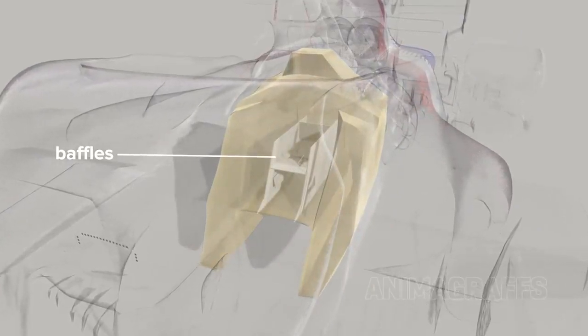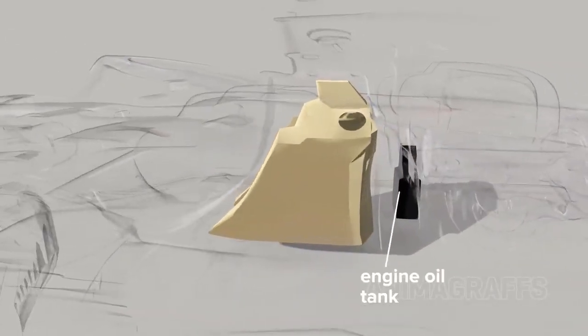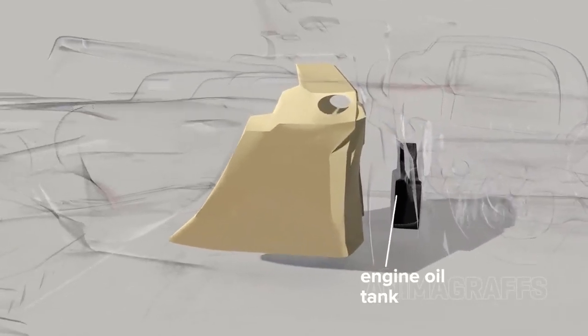The goal is to keep the large fuel mass centered and low, and also to prevent foaming and fuel pump starvation. The engine oil tank is placed between the engine and fuel cell.